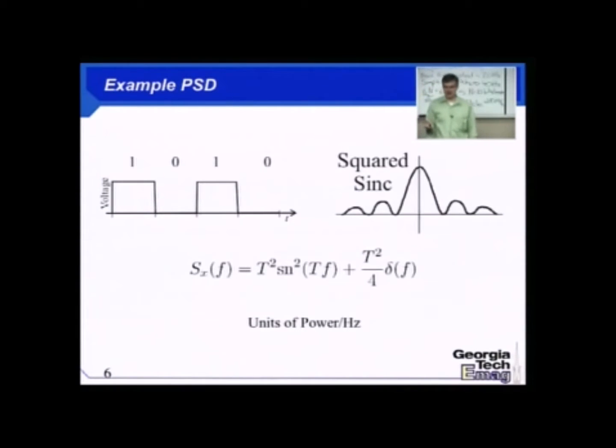So wouldn't it be nice if I had a pulse that I could put digital information on? I could key it with positive or negative values that was bigger than a symbol period. Does that seem like a contradiction? Well, in most cases it would be, right? If I had a pulse that was bigger than the symbol period, then my pulse would bleed into the neighboring pulse slots, and I would destroy the ability to detect the amplitudes of my pulses. Unless I do something very, very clever.